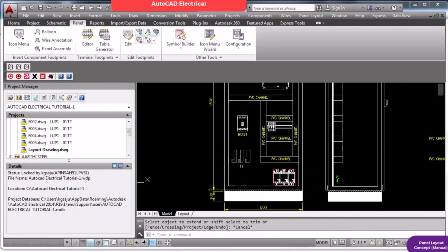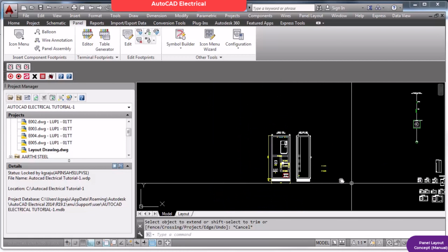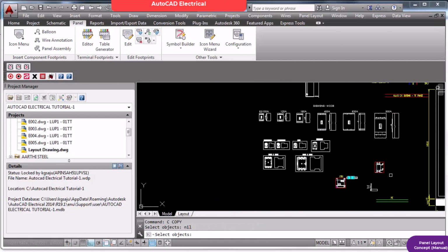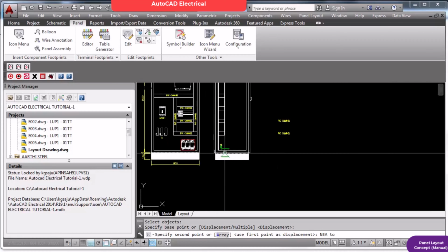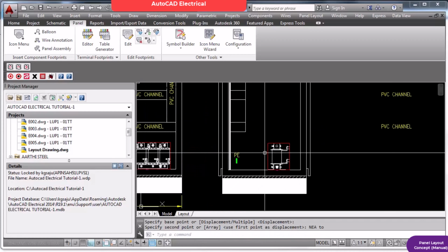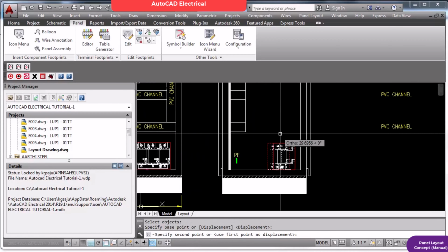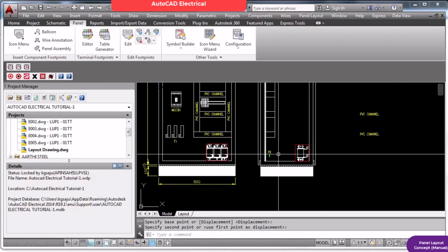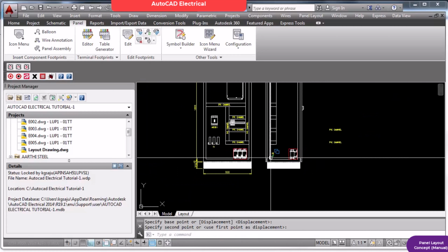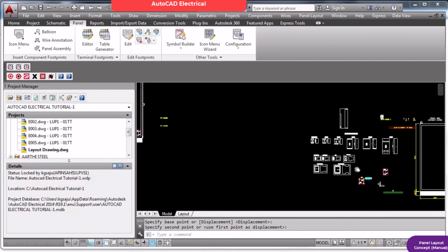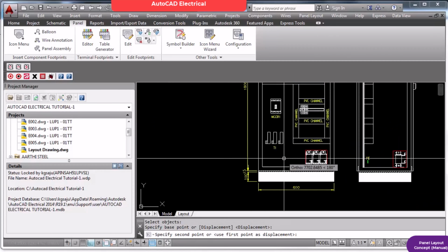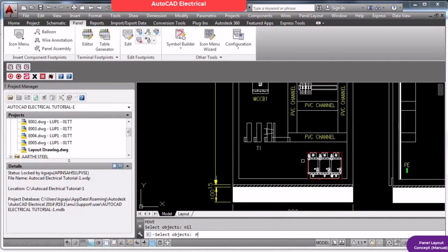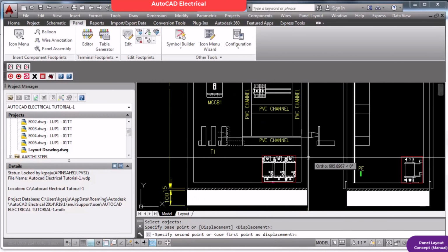You have to visualize the things. I'm looking from the left side view. I'm now viewing from the left side of this panel. So what else will I think? This is overall. Now at the bottom I can see a choke, so I will bring a side view of a choke here. I will keep it somewhat in the front side, because my cable entry is through the bottom, so it won't restrict my gland plates for smooth cable entry. Now these bus bars, I have a block for that too.